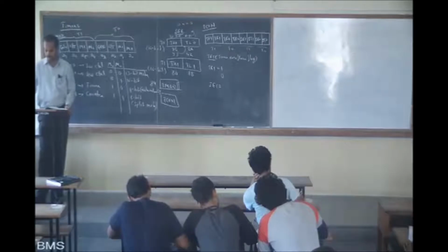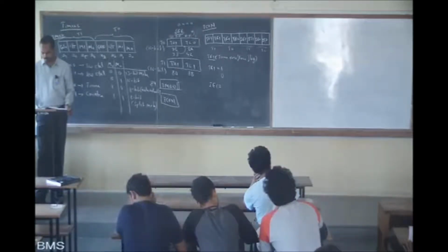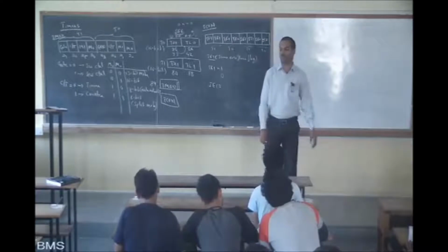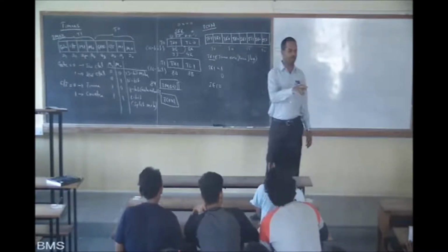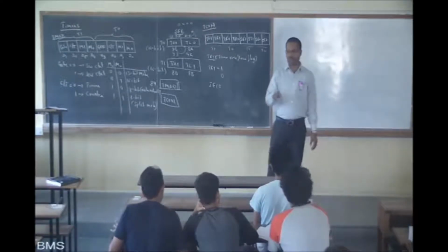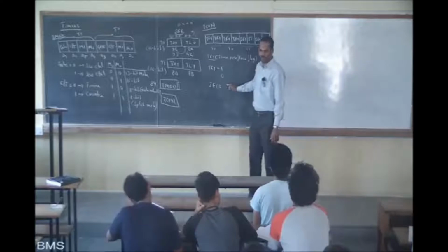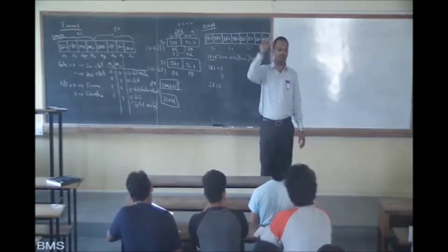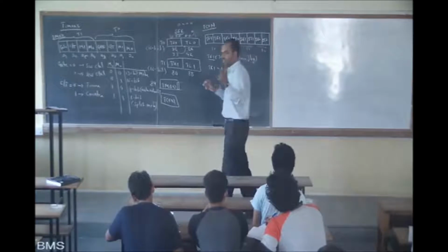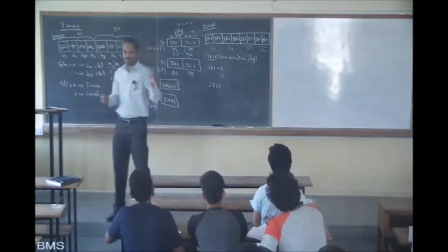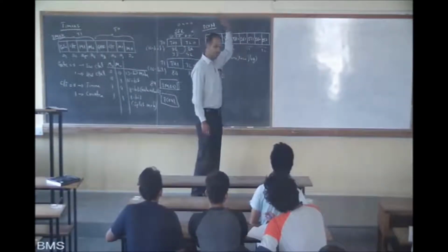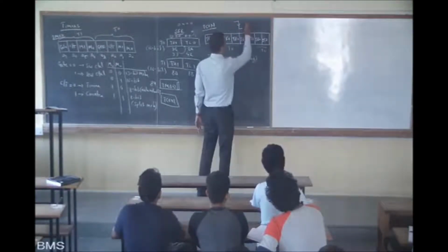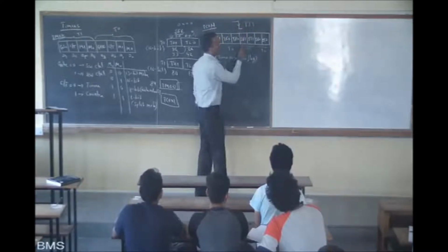Set by pin 3.3. See, P3.4 and P3.5 are timers T0 and T1. Above that, P3.2 and P3.3 are there. So 3.2 is interrupt 0, 3.3 is interrupt 1. So IE1 is connected to interrupt 1. Guys, listen to this: if on interrupt 1, that is pin 3.3, there is a high to low pulse, then this will start.